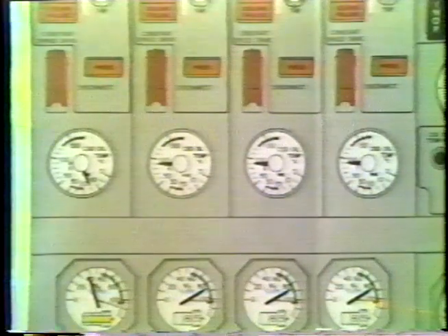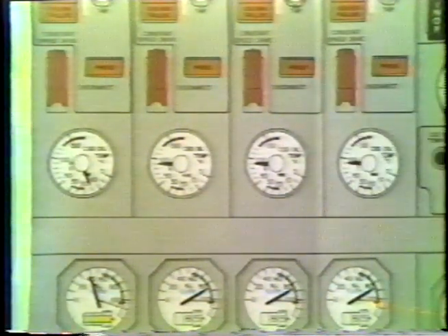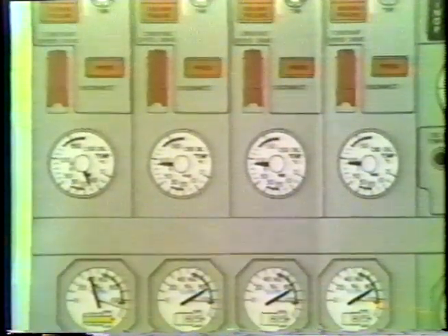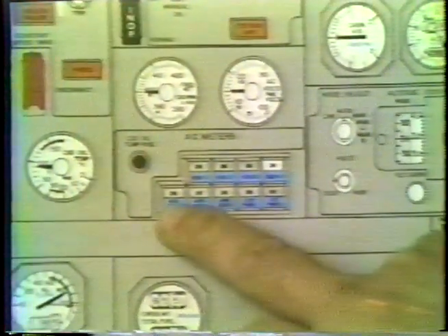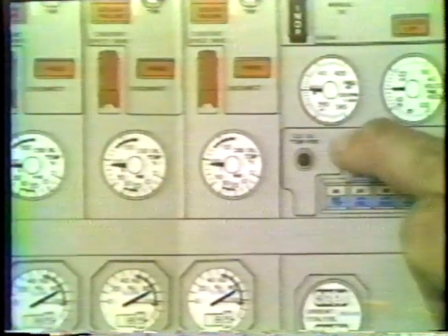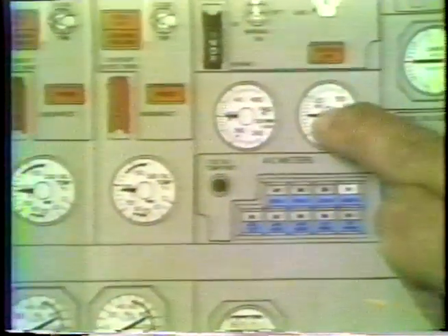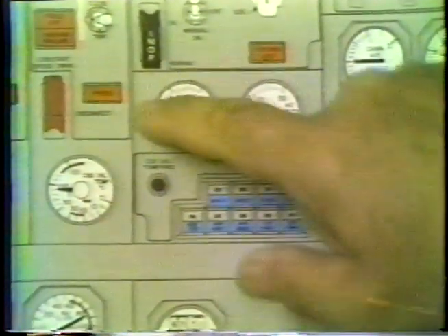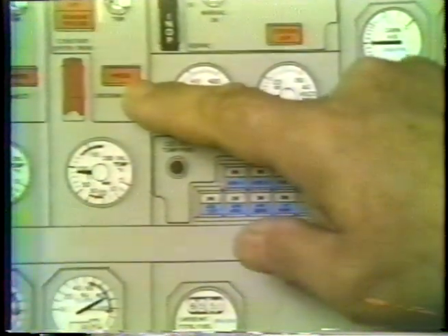When you want to operate the disconnect switch, you should select the generator you wish to disconnect with the AC meter panel and hold the generator test. Upon activating the disconnect switch, you will see an immediate drop in RPM and PMG of the generator. And if the low pressure light was not already on, that should also come on, assuming the engine is running.